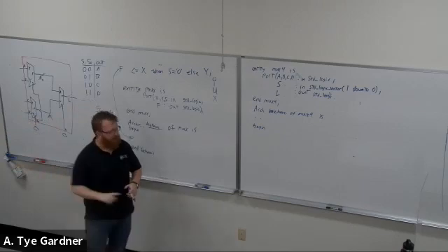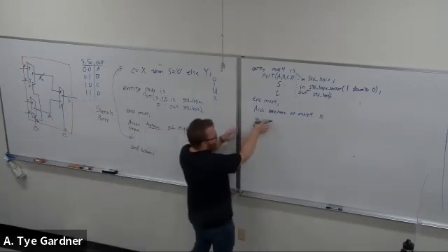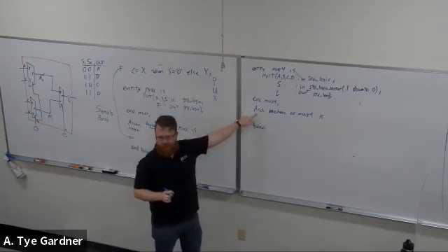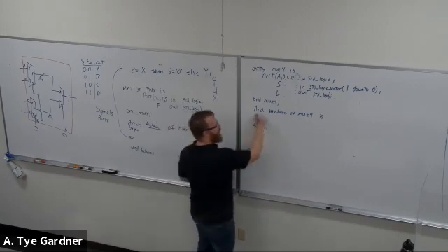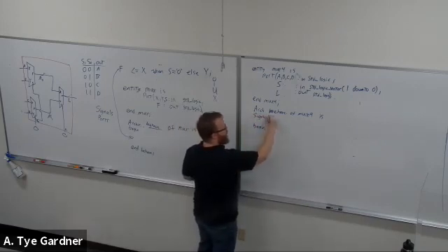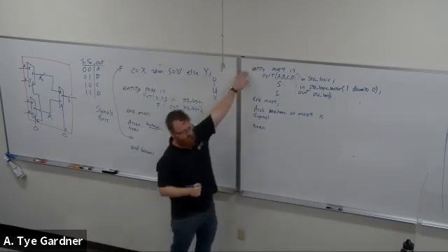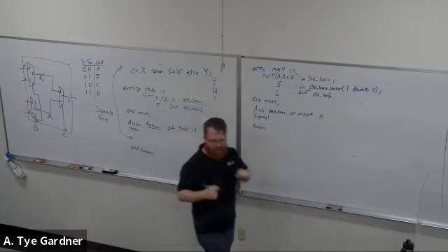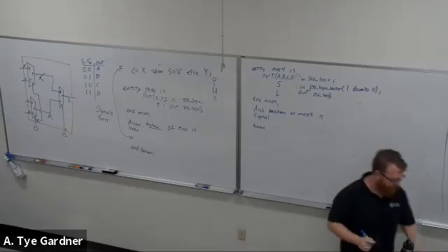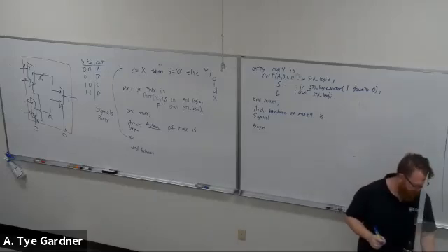Okay, so what I do is I come over here between the architecture. The architecture is the only thing that cares about what its name is. So between the architecture and its begin, I write signal. Just like the entity warns the program that the entity is coming, signal warns it that there is a new signal.